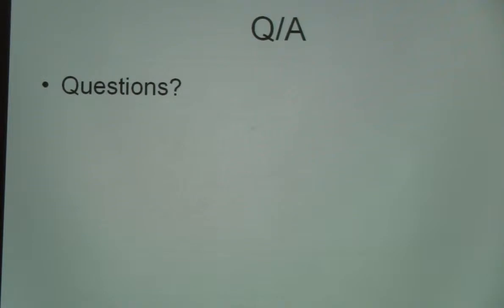The Pi only has one UART. So you could buy one of these UART chips they were talking about, and it's probably I2C to talk to it. So you would say, send this character to UART 1, send this string of characters to UART 3.